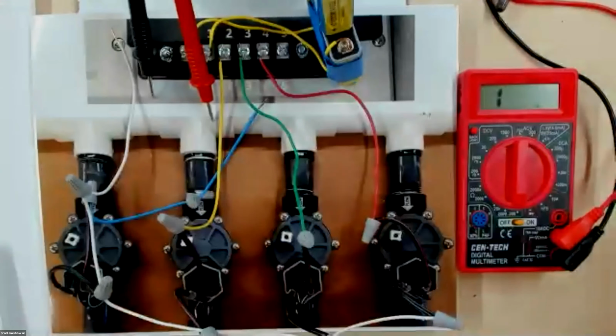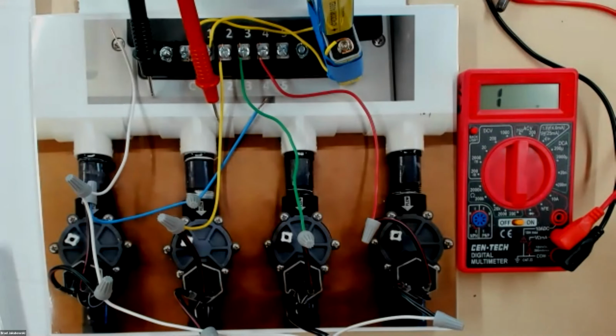Now, question for you. Testing AC voltage with the controller is a little bit different than checking resistance, like checking the resistance of the solenoid. When we're checking the resistance of a solenoid, we need to have the power of the controller turned on or turned off. Which one is it? On or off, if we're checking the resistance? Right, Dave, we need to have the controller turned off. Off. Very good, thank you.